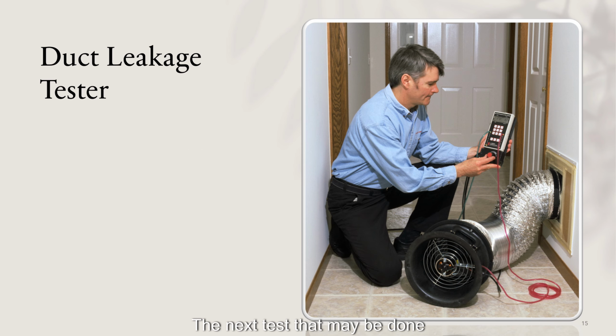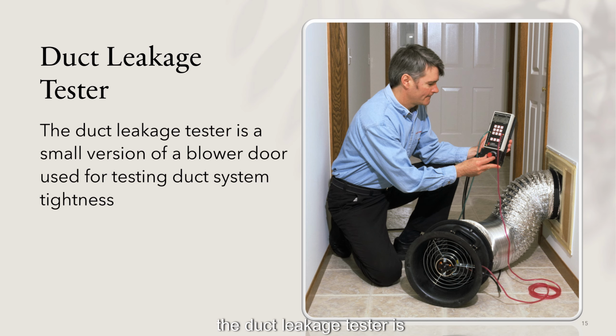The next test that may be done is a duct leakage test. The duct leakage tester is a small version of a blower door used for testing duct system tightness. Similar principle, we're going to pressurize the system. We're going to look and see how much leakage is developed or how much leakage we see per se in the ductwork, and then we can go ahead and make recommendations on fixing that leakage.